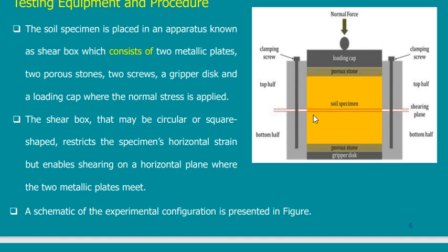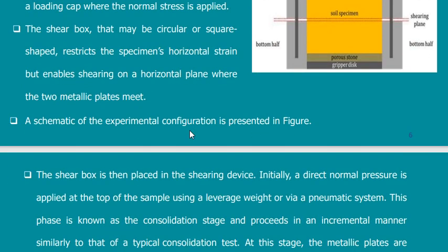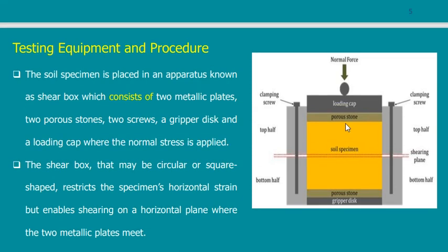So if I am letting the water carry part of the vertical load, then when it comes to the shearing force, water will not carry anything. So I'm just putting the sample in a condition that does not resemble the real condition. So this is the first thing, that when I put the normal force, I should allow the water to come out of the sample before putting the horizontal load.